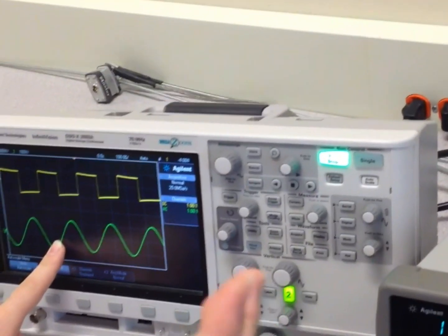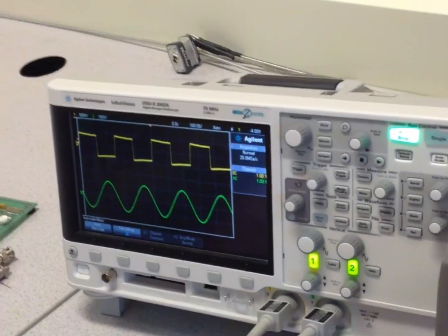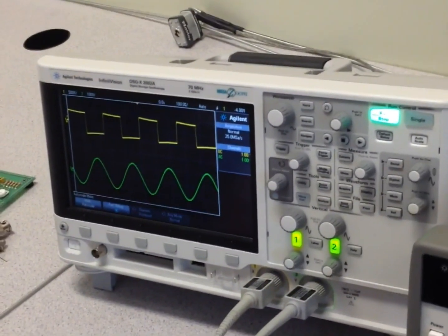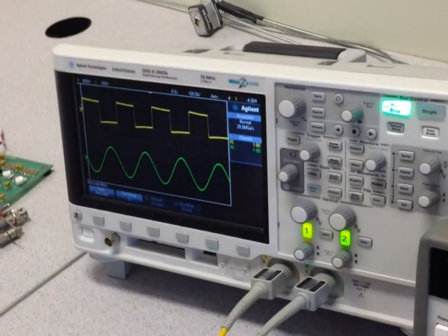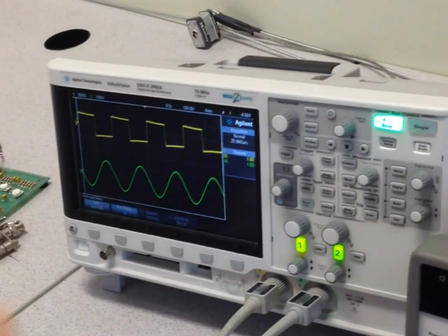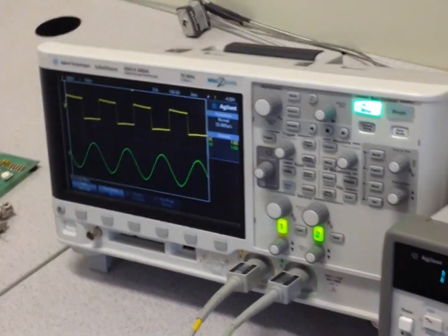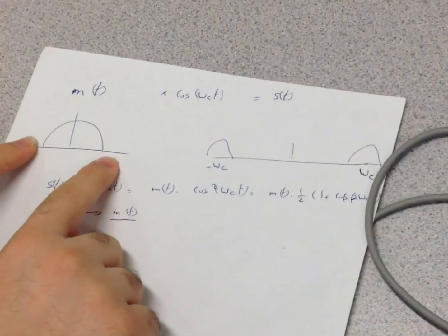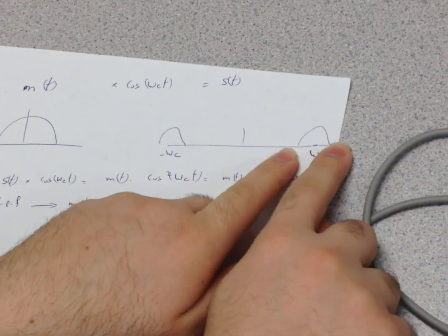What we do in double sideband suppressed carrier is just multiply both to each other. When we do amplitude modulation, where we send the carrier, we multiply the message by the carrier and add the carrier. So my message has some frequency band here. When I multiply by the carrier, the same components appear around the carrier, away from the 0.